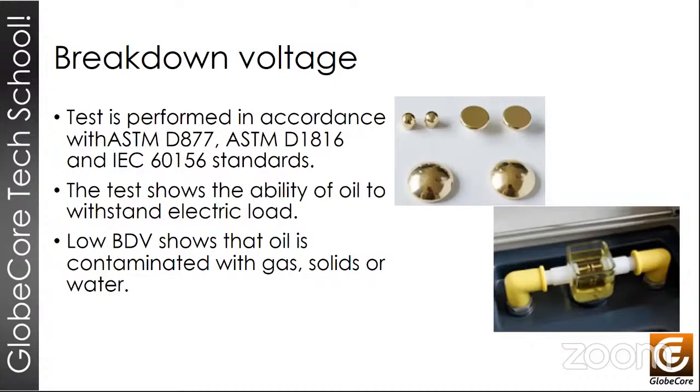It's common for transformer oil tests to be used interchangeably, but there are characteristics that define the ideal context for the application of each specific one. All breakdown voltage measurement methods have in common the fact that they report a voltage value at which an electrical arc occurs in an insulating fluid. But the shapes of the electrodes we use can cause the tests to vary in their focus. For example, ASTM D877 is a test that is recommended for new oils, although it's quite normal for different laboratories around the world to still continue to use it to diagnose energized operating transformers.